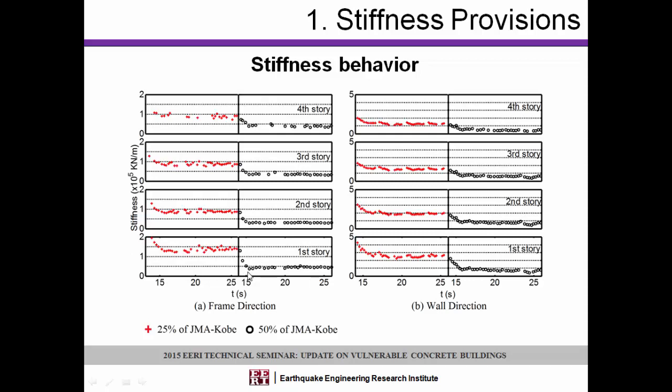So this is a big stiffness change just due to cracking, not even yielding of the building or any real damage. And we see the same thing in the wall direction. You have a drop here and another drop there in the subsequent ground motion. So that was a big eye-opener. I mean, we expected to have some drop. Things soften as you crack, but this is a substantial drop that we've seen.